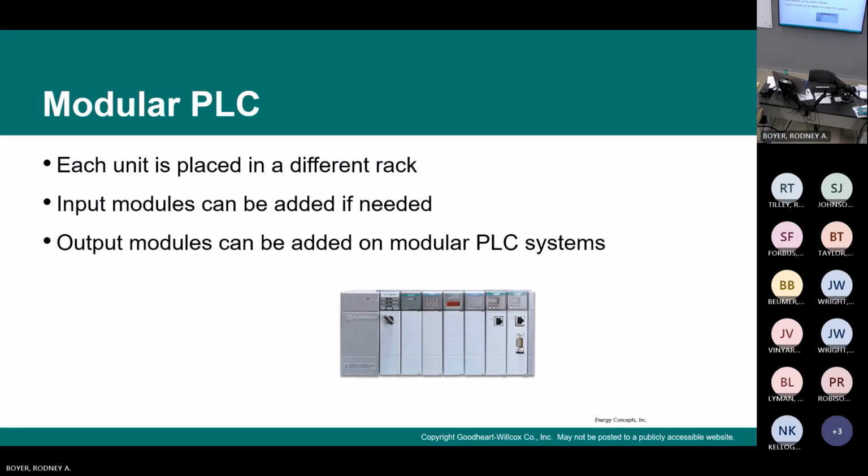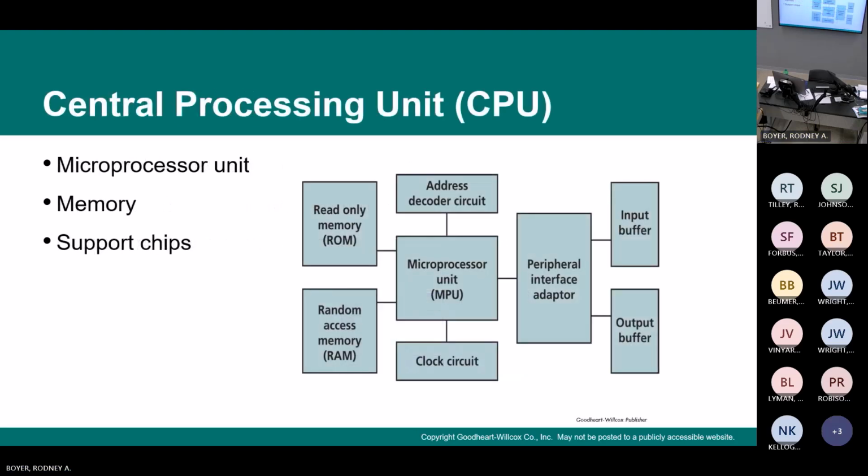And then this module has the mating connector for, you know, if there was another module sitting next to it, it would plug in here. And so on the Micrologix 1400, this is not going to be on the quiz, but it's still good to know. On Micrologix 1400, you can have a maximum of 7 expansion modules. Any combination that you want, but a maximum of 7.